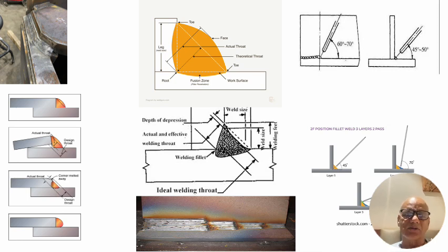Here by gravity it is going to fall down, so we are deliberately putting it onto the earlier fillet, and the angle is 70 degrees. So this maneuvering of the torch angle, weld angle, or even in submerged arc welding when we place our torch or the nozzle, in the other direction it has to be 60 to 70 degrees.